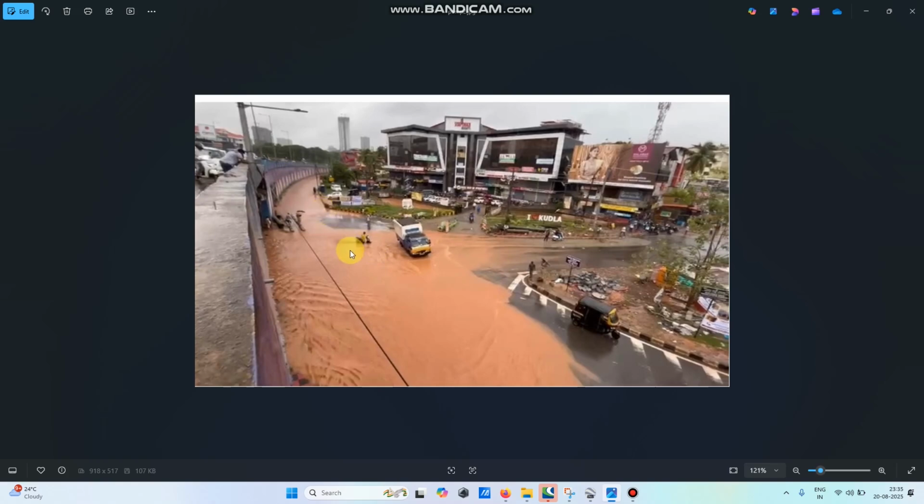But when you observe this connecting road, it has a very small amount of stagnation of water, or almost zero stagnation of water, on this connecting road. So it could be the case that this road is on grade, and this underpass is more likely a possible case of a sag point. So this underpass is in the sag point.